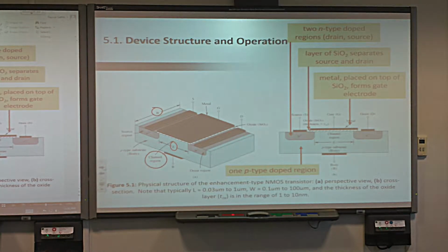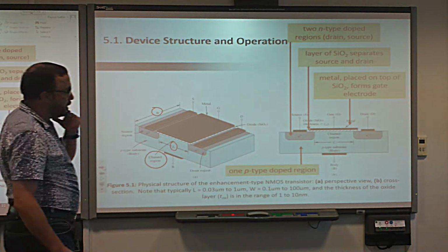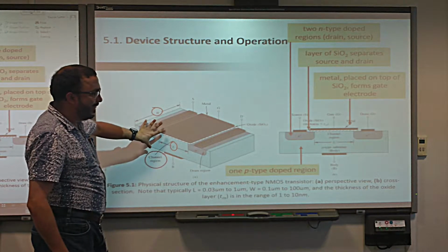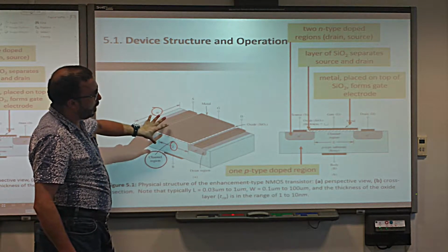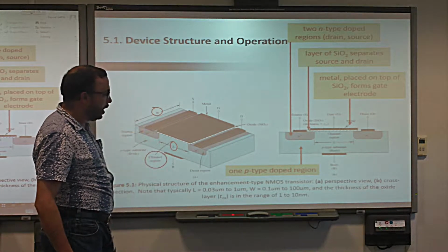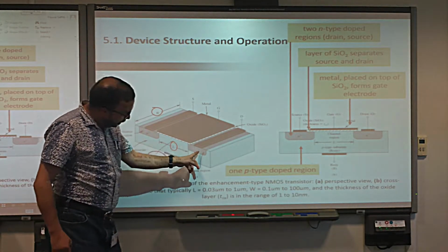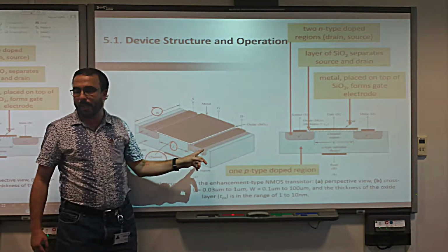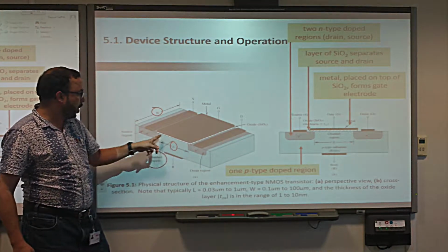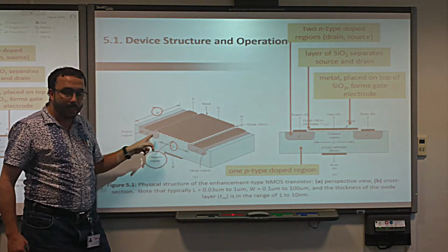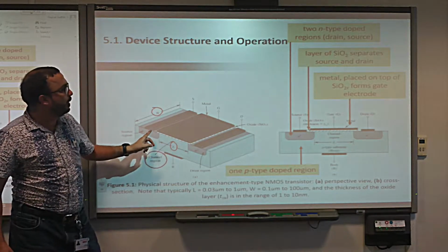Okay. All right. This device, or this transistor, we call it NMOS, N-type MOSFET. Why? Because basically the source and drain are N-type. Or later on, or soon today, we'll discover also that the channel that forms here is an N channel. That's why we call it N-MOSFET.